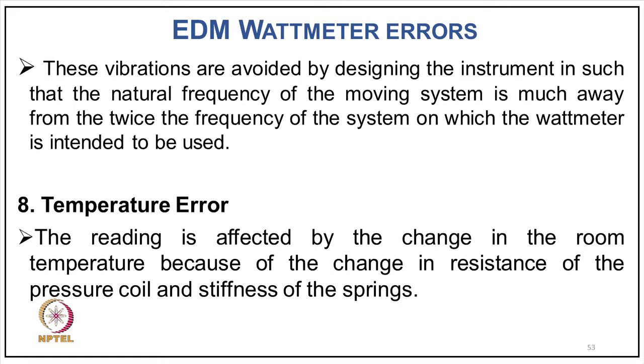Now, coming to temperature error. The reading is affected by the change in the room temperature because of the change in resistance of the pressure coil and stiffness of the spring.